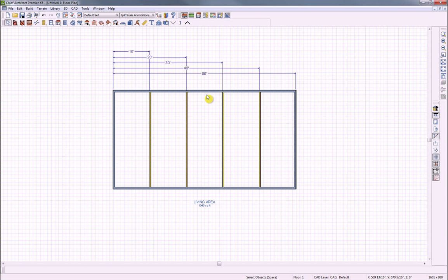So you can see that on your plan, this can take up a fair bit of space to get these baseline dimensions coming out, and depending on what you have inside your plan, it can start to get cluttered. The new dimension tool that we have here is for our running dimensions or cumulative dimensions, and if we use that tool, I'm just going to do a quick line across, you're going to get the same information as our baseline dimensions, but in a fair bit cleaner of a look here.